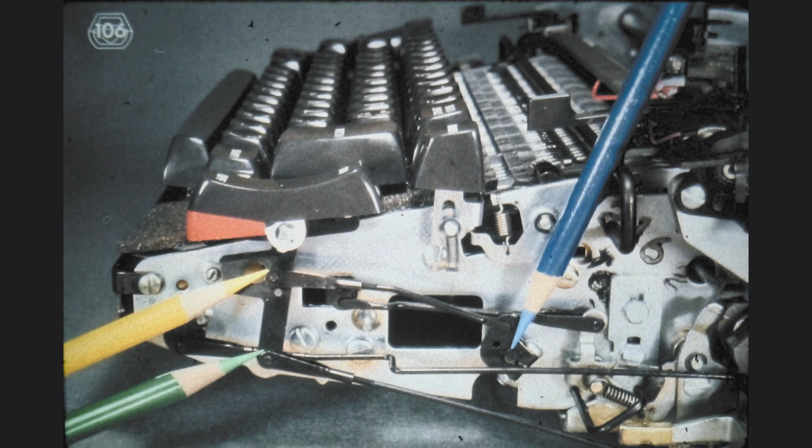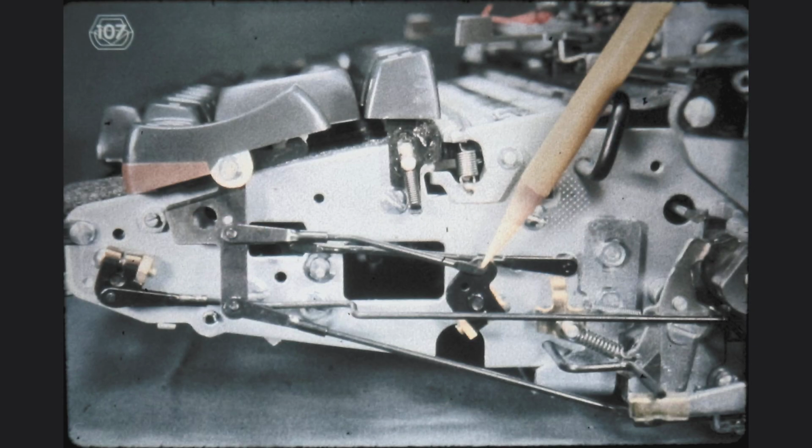Notice that when the switch is on, as shown here, the rear tip of the lockout bail link, at the yellow pencil, is positioned to the front of the lockout bail indicated by the blue pencil. Now let us adjust the on-off switch positions. First step, when the switch is off, the on-off key top must be aligned with the character key tops. Take a moment to perform or check these adjustments on your machine.